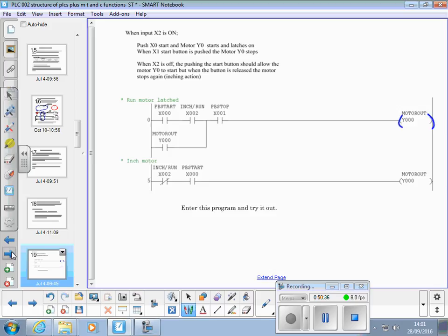No, because when you wire stop buttons, Mike, you wire them normally closed. Remember from last week, on your rigs, the red button, the stop one, X1, the input is on when you've got your finger off it, and it goes off when you push it. Yeah?